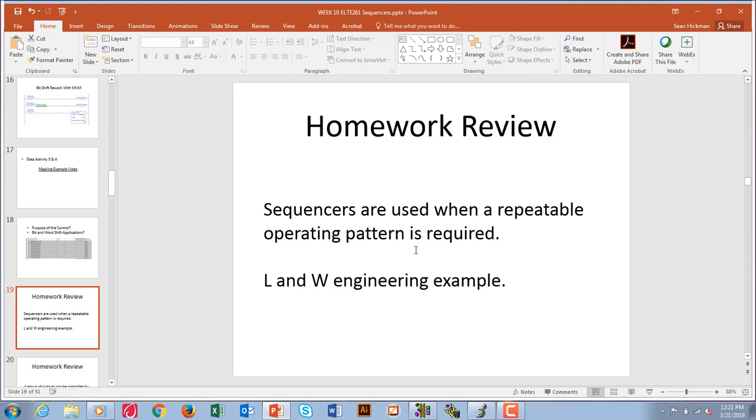And then what it did is it jumped to the next sequencer step. And those 2 ones that were there before, well, they went to zeros. So that means the robot interlock went low and the conveyor stopped. And then it had, let's say, 3 ones came on. And those 3 ones were cylinders. So maybe 3 cylinders came on and held the part. And then the sequencer went on to the next step. Maybe 2 of those cylinders stayed on, so we had a couple of those ones. And then maybe 2 other ones came on at different locations, which were the sealer gun and maybe the drill press or the drill or something. So that's the way that this went through.